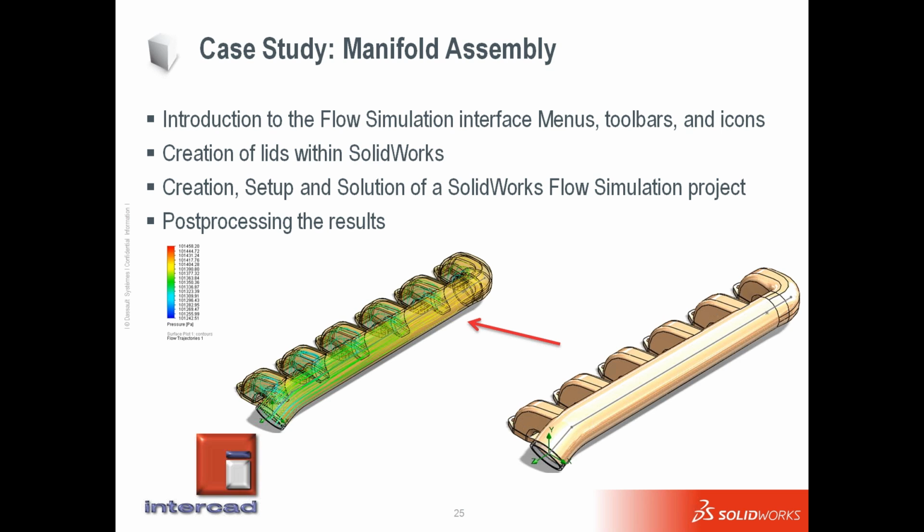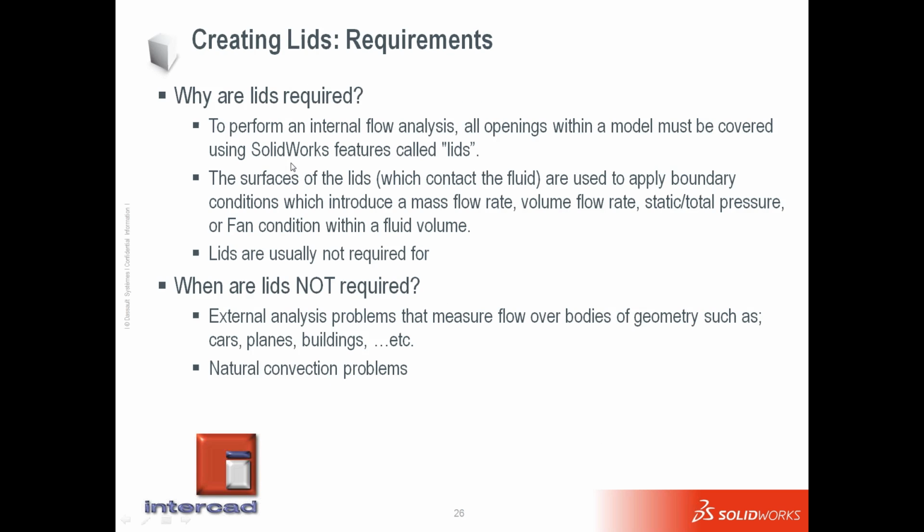But before I open the case study file, we mentioned something about lids here. What is a lid and why is it required? If you would like to perform an internal flow study, all openings within a model must be covered using a SolidWorks feature called a lid. Simply, we close all the openings and exits, and we create the negative volume of the solid we have, telling the software this is the region where the fluid exists.